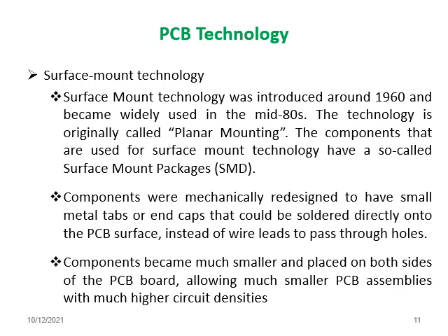For example, a resistor normally has leads on both sides, but instead of leads, two metal caps are added on both sides. After that, the surface mount resistor is placed on the track and soldered. In this method there is no need to make any hole on the printed circuit board. The surface mount component is placed directly on the copper track and soldered.